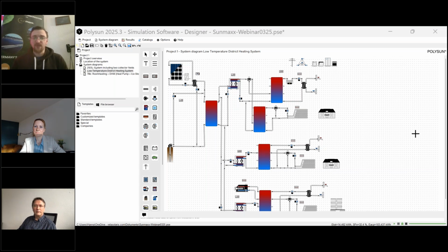So that means if we have bigger projects, there's also always a test drilling, so that we know how the ground is and what the thermal capacity of the ground is. And with these values, I can also go to Polysun to simulate the degree of regeneration and how many drilling meters are necessary inside of the project. Yeah. Okay, thank you very much.